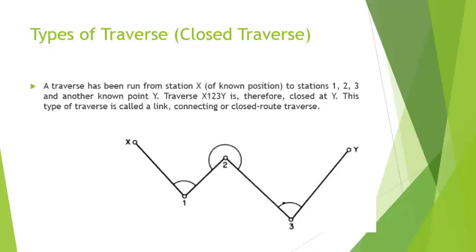The closed loop traverse is suitable for locating the boundaries of land parcels, lakes, and many others that form a polygon-like area, and it is also suitable for a survey of large areas. On the other hand, the link traverse is suitable for traversing a long narrow strip of land such as roads, canals, and coastlines where the return process or making the loop is unreliable.